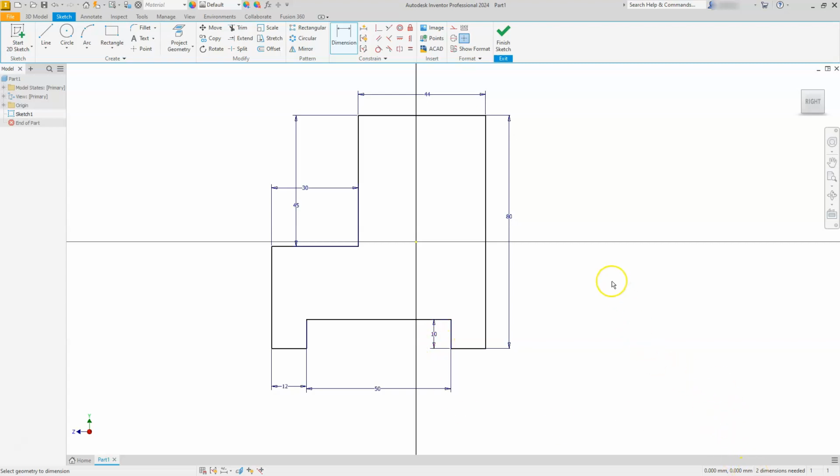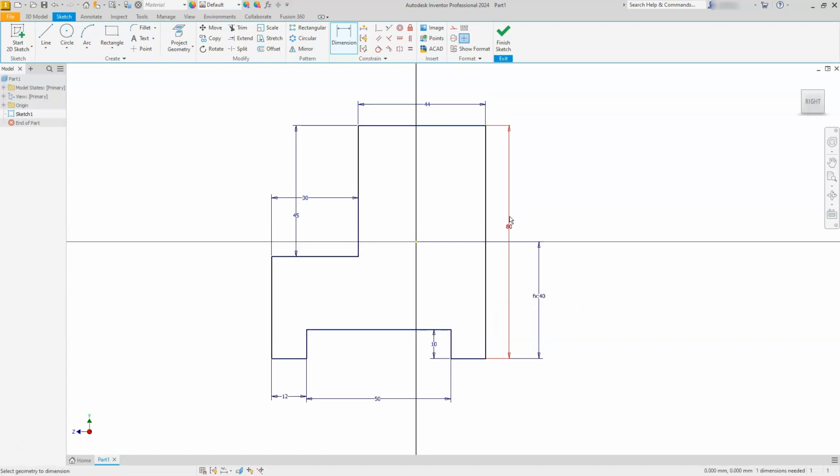And that's what I ideally try to get to, because the last 2 dimensions you're going to need are going to be in reference to your center point here. So let's go ahead and put a dimension from this line here to that yellow dot, or whatever color yours is, and I'm just going to left click and place this. And when I have the edit dimension up, I'll click on the 80, and then go divided by 2. Once I hit enter, you're going to see that now this is a function of this one. So if this number ever changes, it's always going to keep this centered.